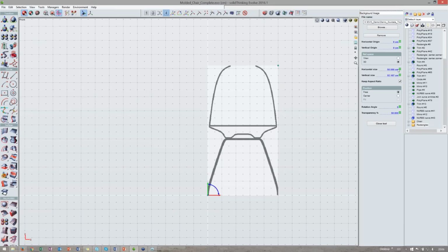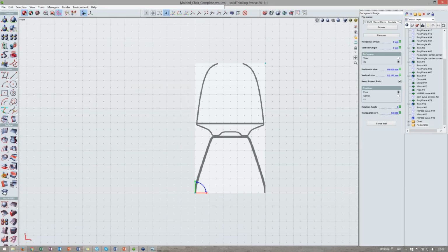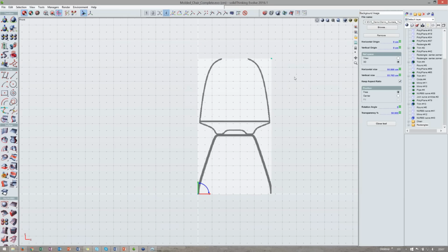In this case, I also want to know maybe a couple of dimensions already. It's just a reference. It's not something that you have to strictly be precise about, but it helps the design process to start with some reference, with some dimensions. So here, for example, I put 50 centimeters for this horizontal dimension. And you can see the aspect ratio gets basically constrained to your original image.